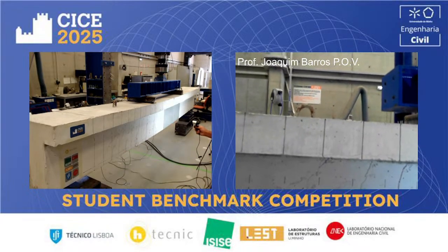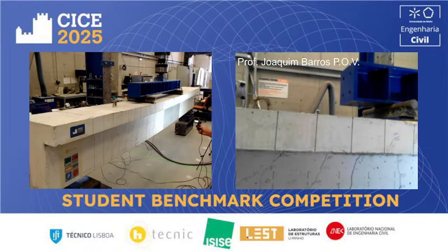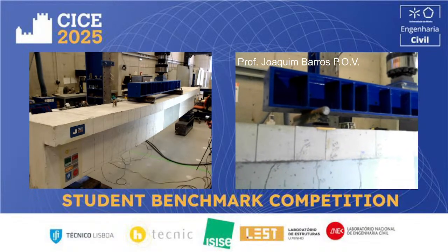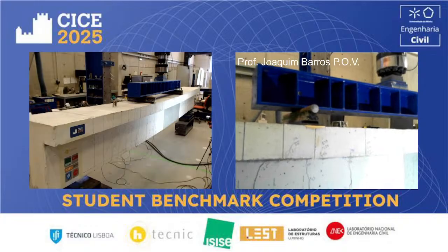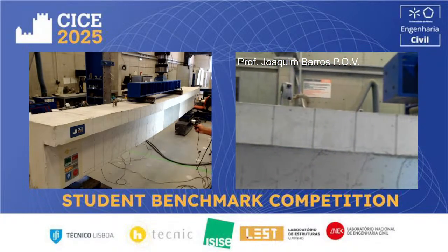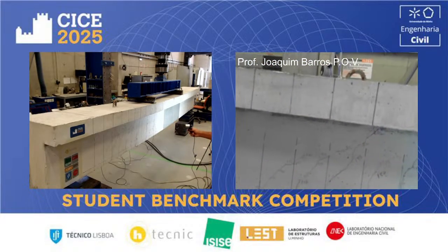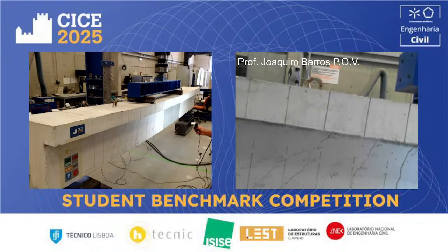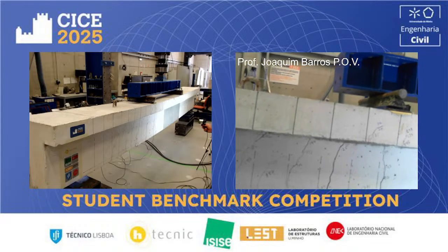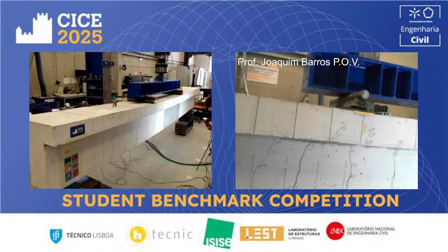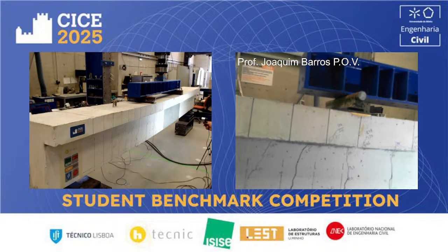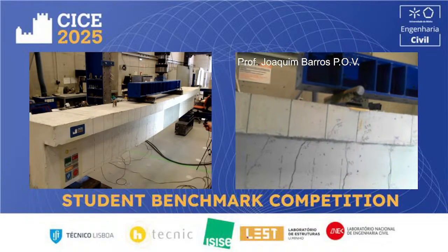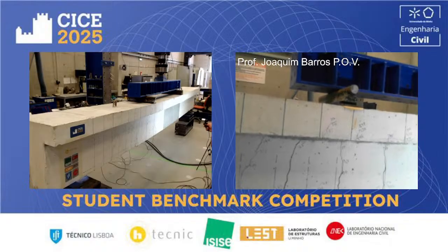Since the localization of the damage is in these principal flexural cracks, the crack pattern within the other cracks is stabilized. So at this moment, all the damage is localized in these main flexural cracks.